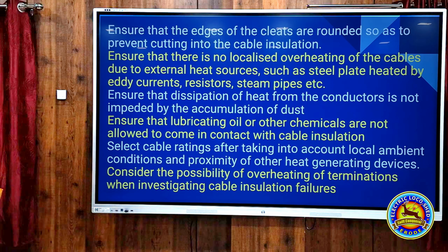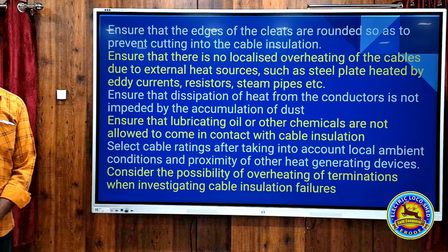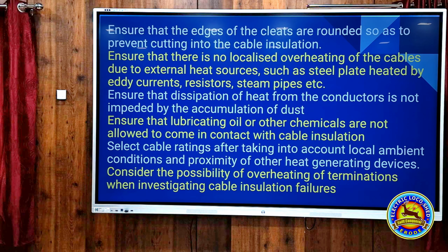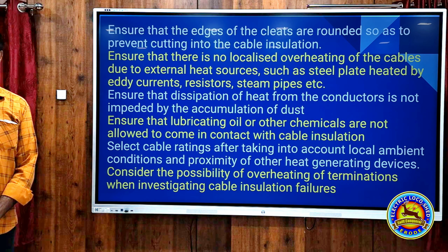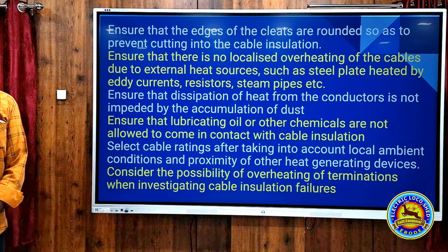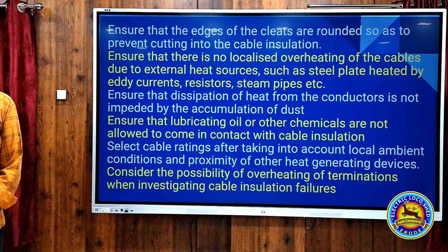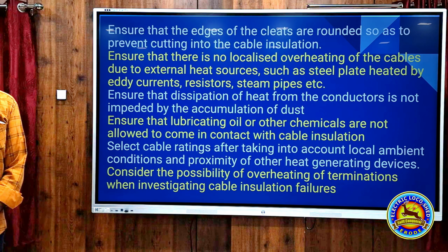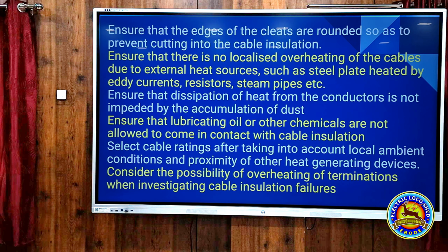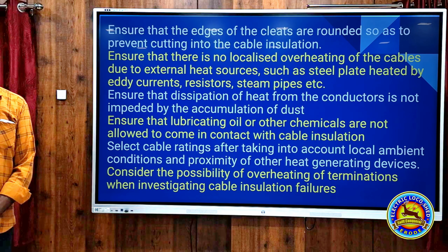Normally the derating factor is some 0.8 or 0.7. The standard rating, if we assume it as 100 amps, and we take the derating factor as 0.8, then the capacity the cable can carry will be 100 multiplied by 0.8, that is 80 amps only. If we want to carry 100 amps in that location, we have to use a higher size cable, otherwise that cable will get heated up and that will cause a fire.